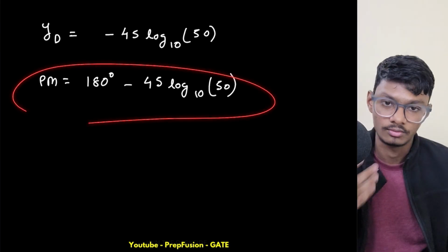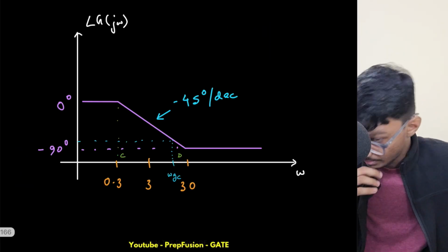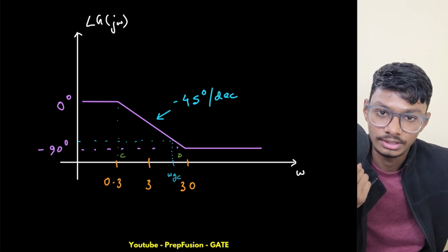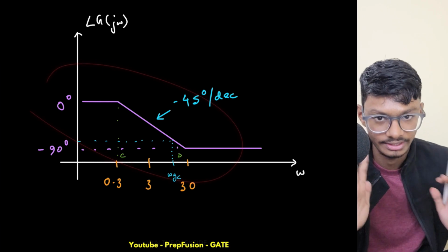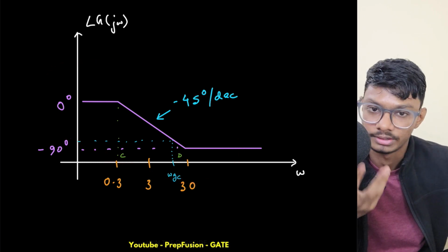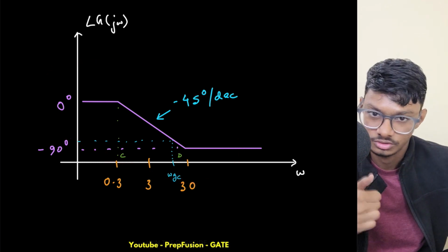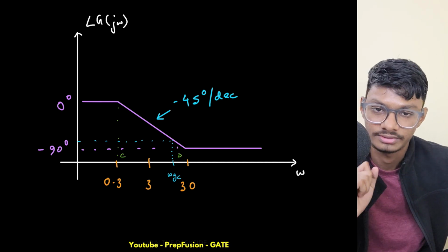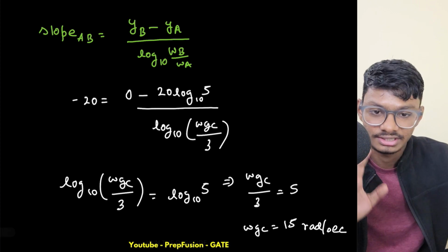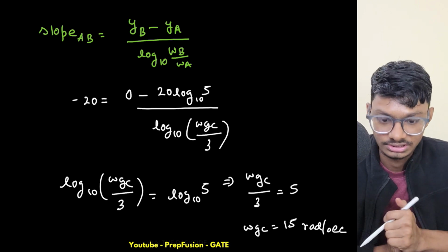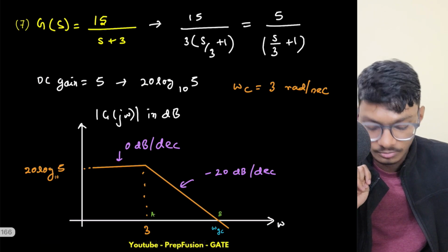So from here you can also calculate the phase margin and gain margin. So gain margin, can you calculate? Is it ever crossing the negative real axis, minus 180 degrees? No, this is never crossing the minus 180 degrees. So gain margin obviously I won't be able to calculate, or phase crossover frequency also I won't be able to calculate. But gain crossover frequency and phase margin I will be able to calculate from these two parts. This was just the basic example of these two, right? Just a basic example. How can we find the gain margin and phase margin from the Bode plots?